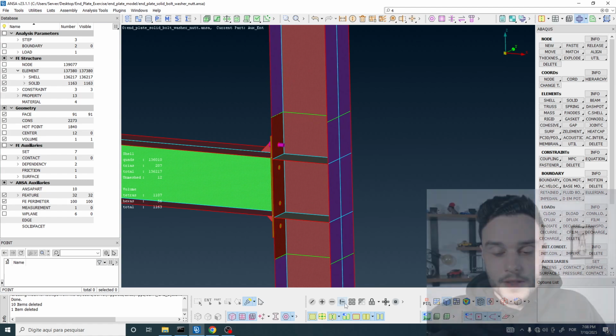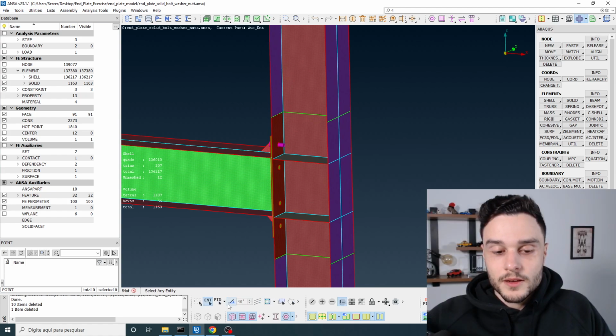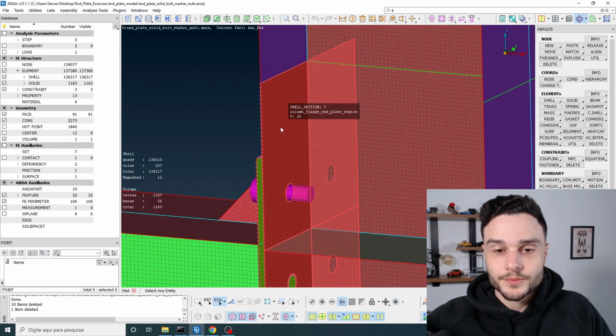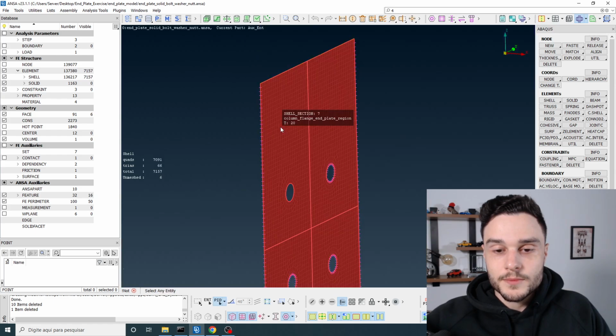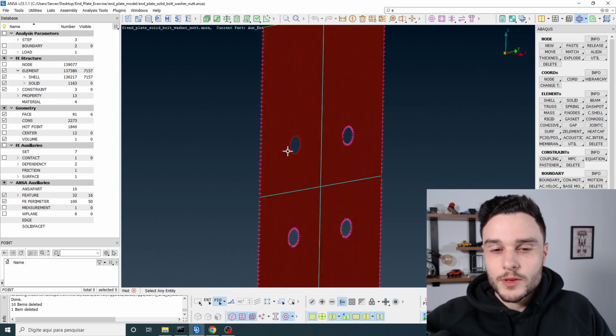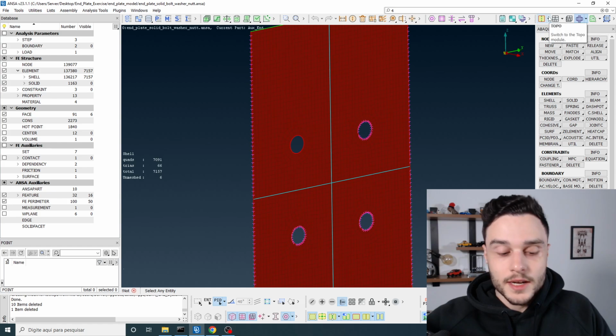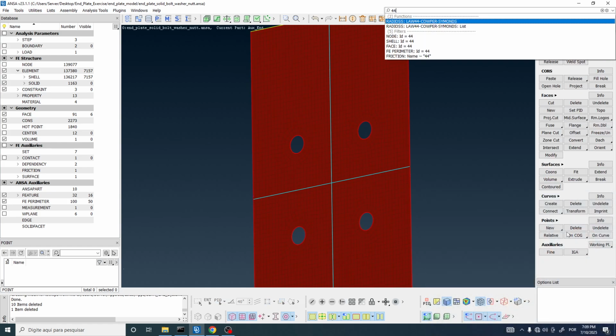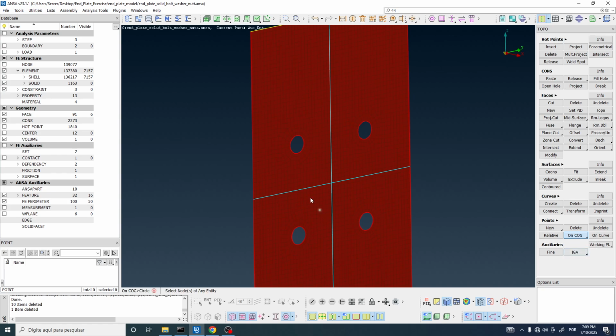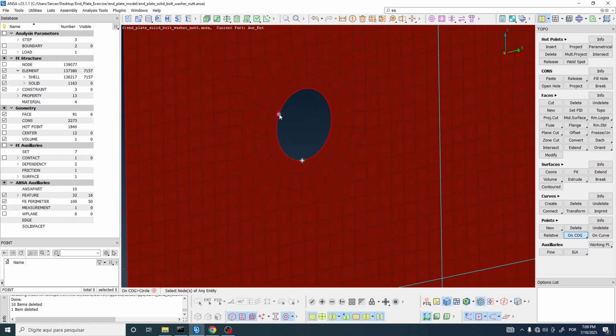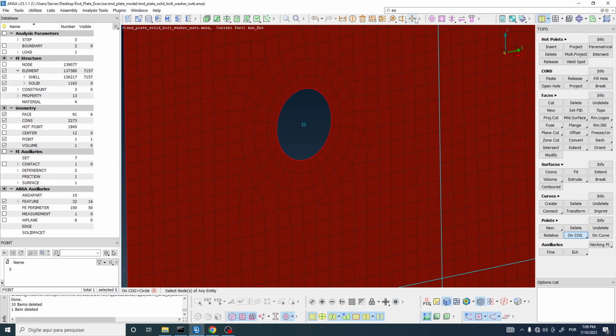Now let's use the knot tool, PID selection mode. Select this PID here, middle mouse button. We are going to use the same technique that we have used before to create the washer. So I'm going to be faster here. Select classic topo module. Let's create a point on COG of circle, zoom in here, select 3 nodes that are part of the circle, middle mouse button, and then let's use the move tool, transform, move, select entities, select this node, middle mouse button.